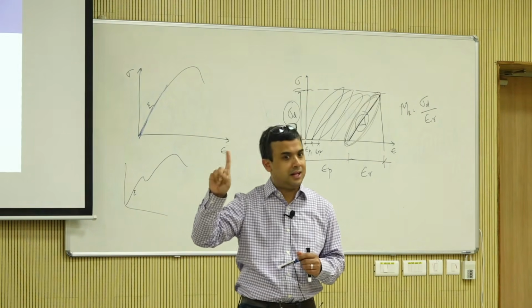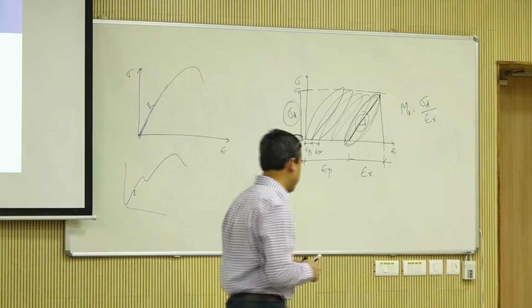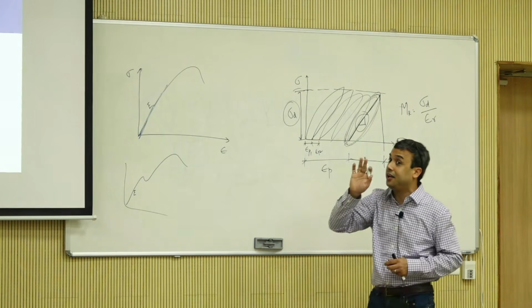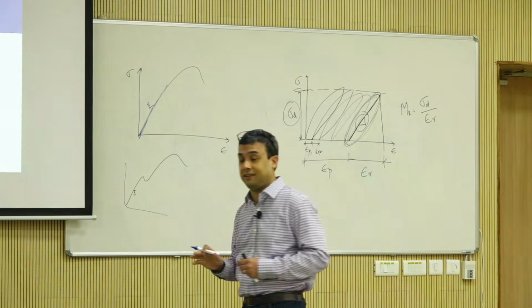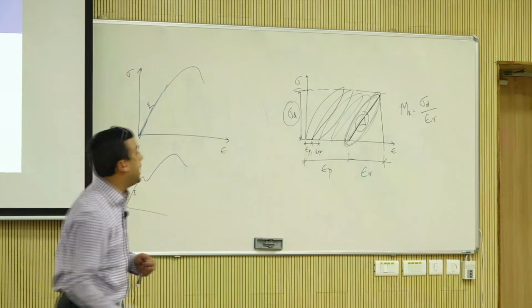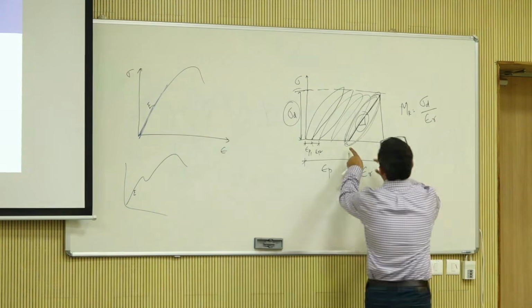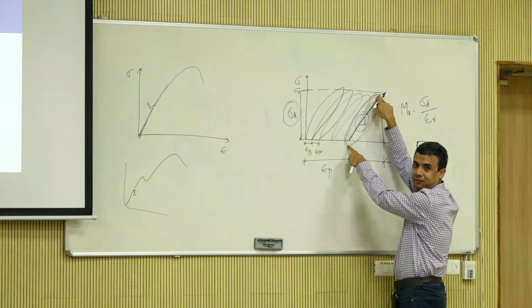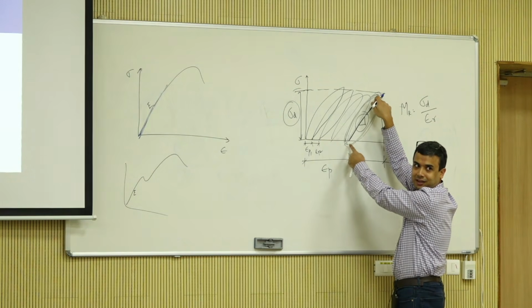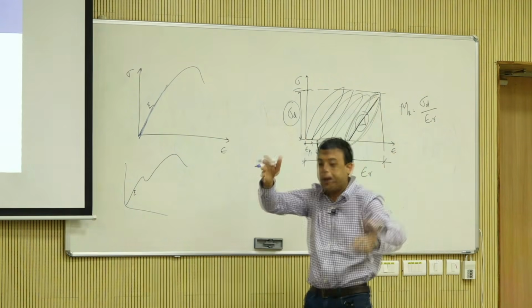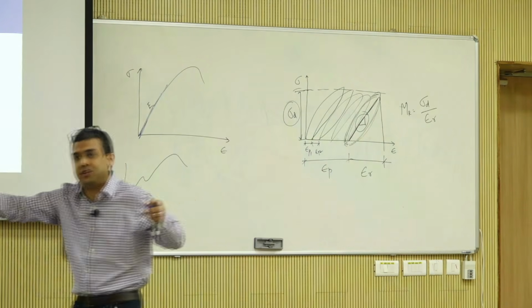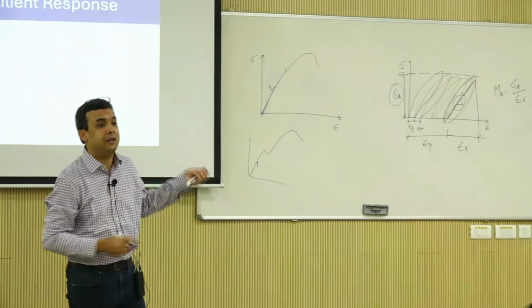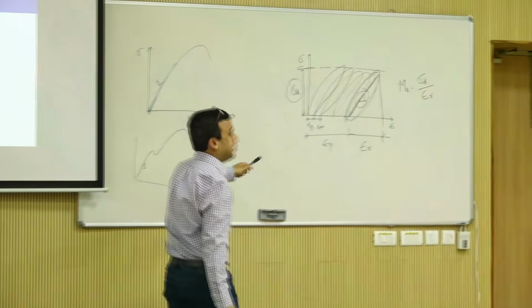Okay, that's first. Yes. So that's recoverable strain only under repeated loading. That's the right answer partly. But if you look at it here, the sample does not know anything about recoverable or plastic. For the sample, it is all elastic, right? That's true when you know the whole picture. I know I'm picking here, but that's the whole point of understanding it from a mechanics point of view.